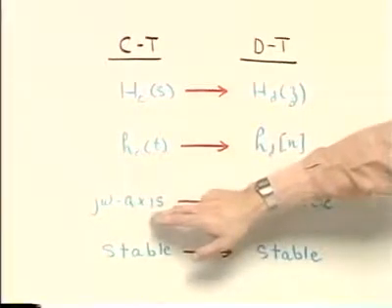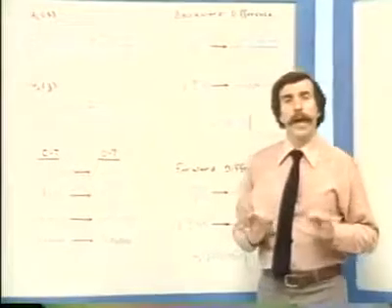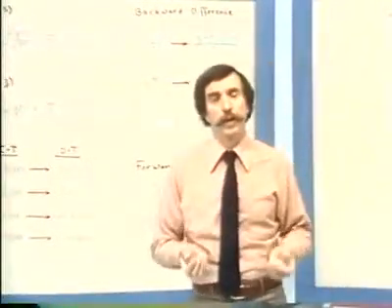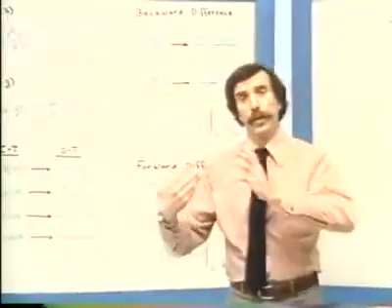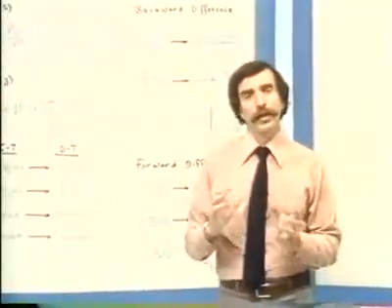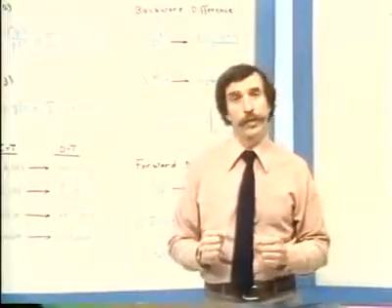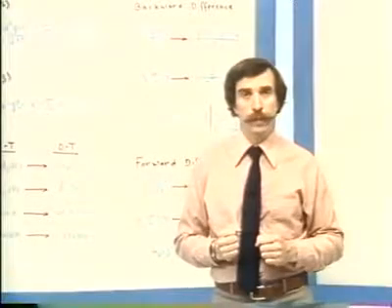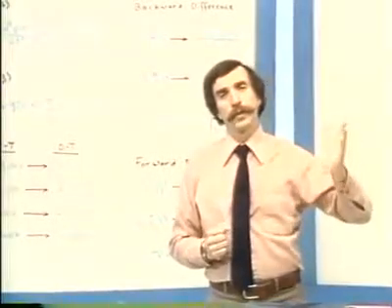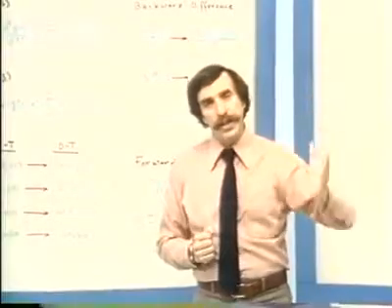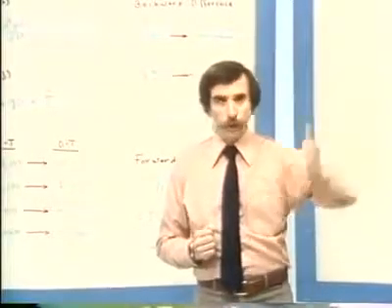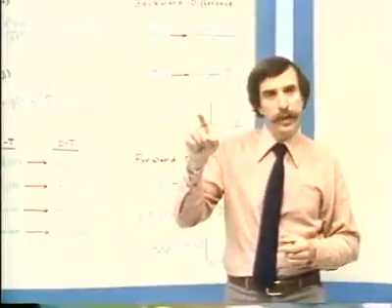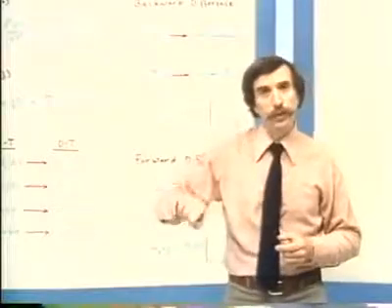In particular, if we are mapping a continuous time filter with, let's say, a desired or desirable frequency response to a discrete time filter, and we would like to preserve the good qualities of that frequency response as we look at the discrete time frequency response, then it's important that what happens in the S-plane for the continuous time filter along the j omega axis relate in a nice way to what happens in the z-plane around the unit circle.